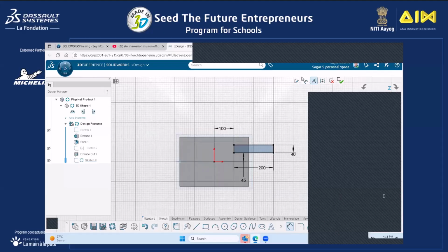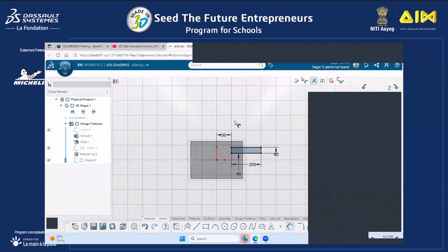How to make the screw of the bottle cap. So you want to provide the threads. Abhilash sir, you want to know how to create a thread on the bottle cap. Okay, for that I need a circular face. So I will delete these sketches and create a center-based circle.